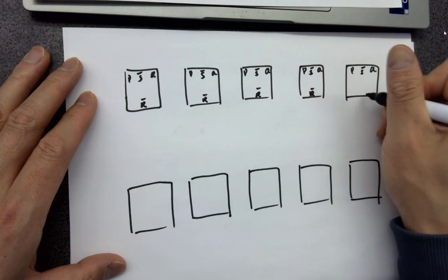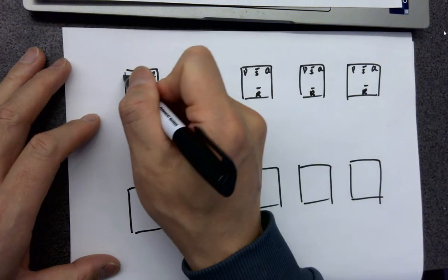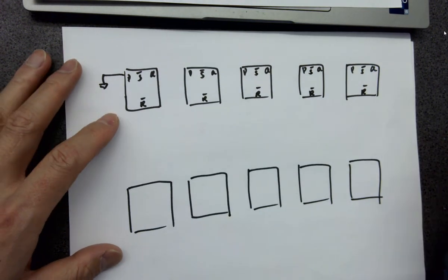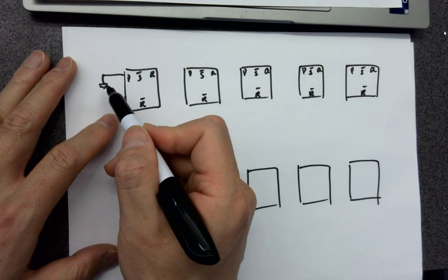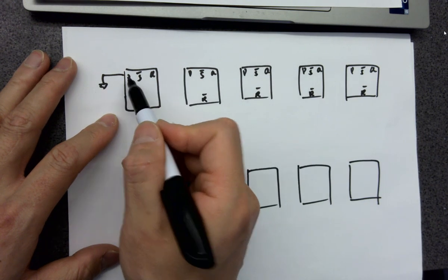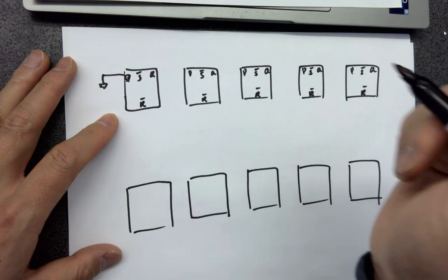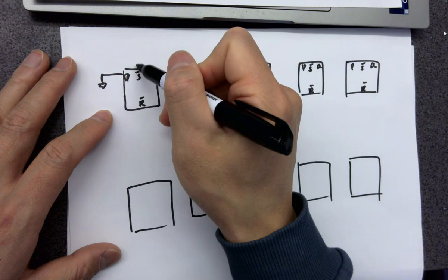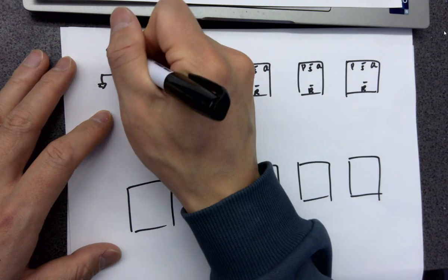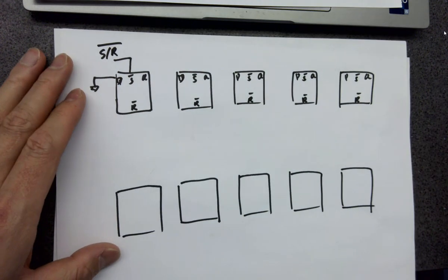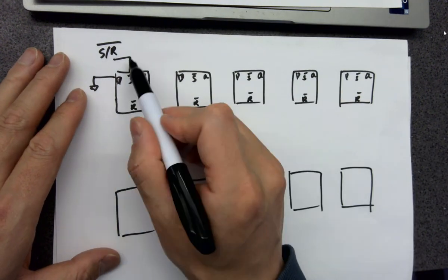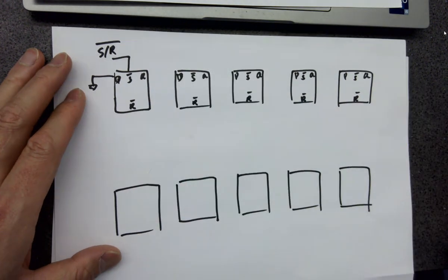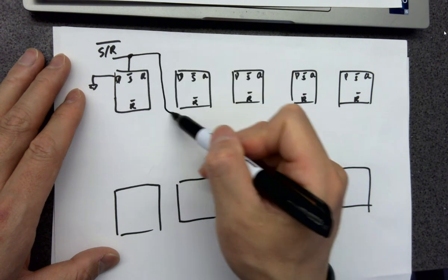So you ground the first D because eventually after reset everything, when you're passing 1 to the right and you're adding 0 to the front. So that's why you're grounding the first one. So you want to shift the 0 to the right, or add it to the left-hand side of the 1. And there's a set and reset, and it's active low, keep in mind. So set is setting the first one and resetting the following ones. So you're getting a 1 and zeros as an initial state of the ADC conversion.